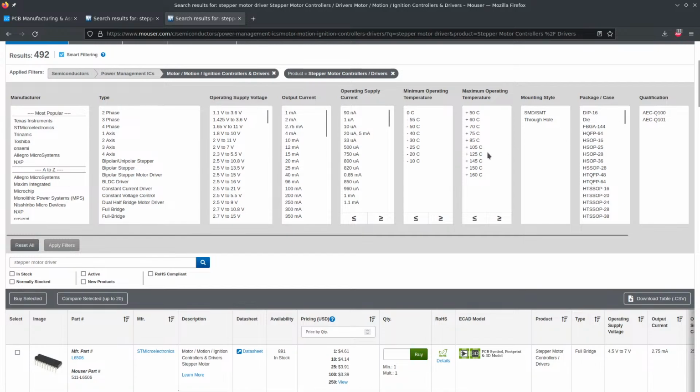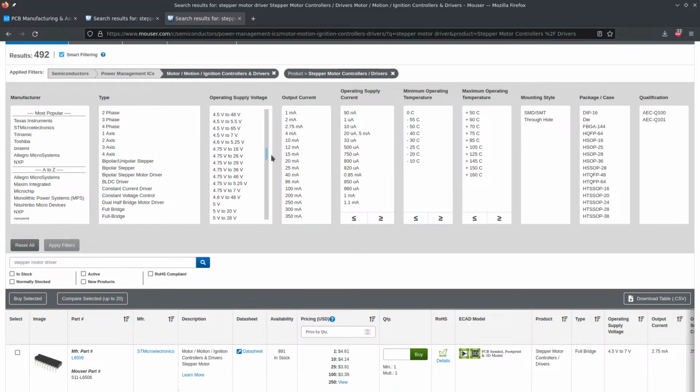And then there are all these things like, what voltage are you planning to use? Which we don't even know yet. Recommendations for stepper motors? 24 volts is nice. Yeah, 24 volts works. This particular one, the DRV8825, which I found actually goes up to 42 volts, which is a weird number, but it's great for 36 with some headroom. The higher voltage you can deliver, so in the stepper motors, when these move, it literally has a coil in there. So it has a permanent magnet in there, but also a coil.